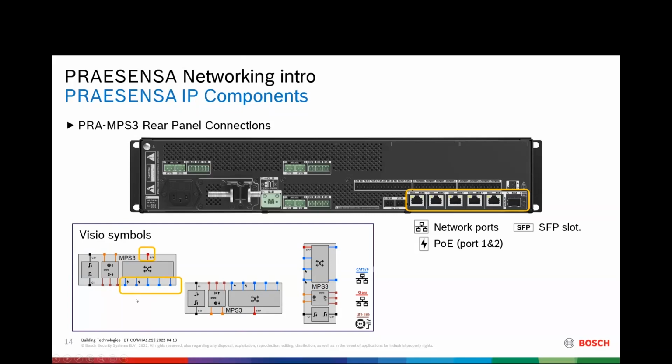Yeah, and that are these ones. So that means that you have these 5 Ethernet ports here, the RJ45 in blue, Cat5, 6 in blue, and 2 of them are then PoE power device interfaces, and you have then the SFP for the fiber connection. And they can all be used in parallel. So there's no dual personality port here. Everything is individually connected to the system.